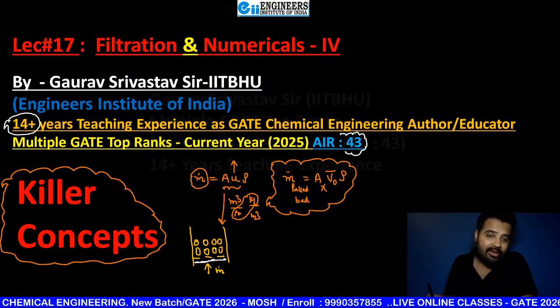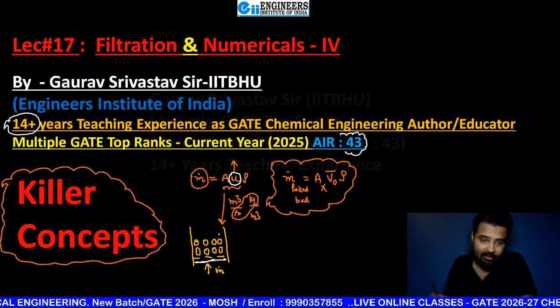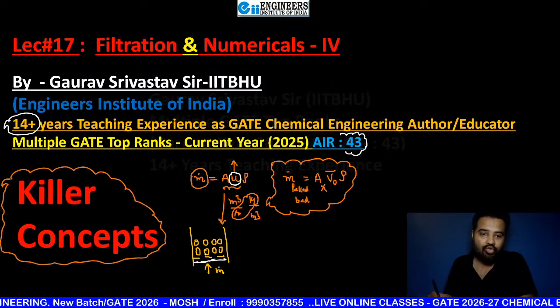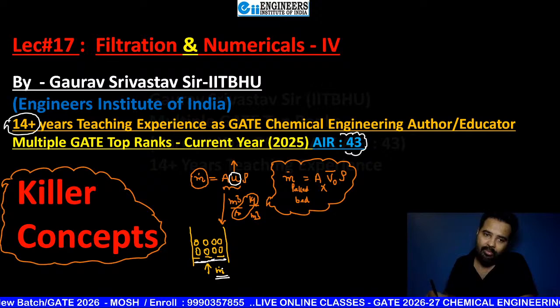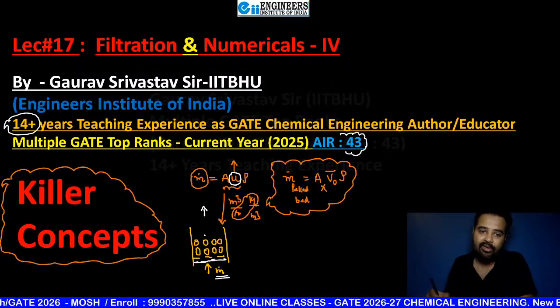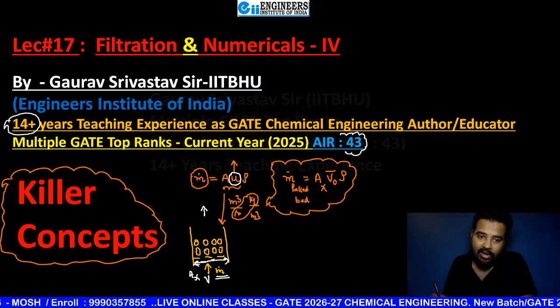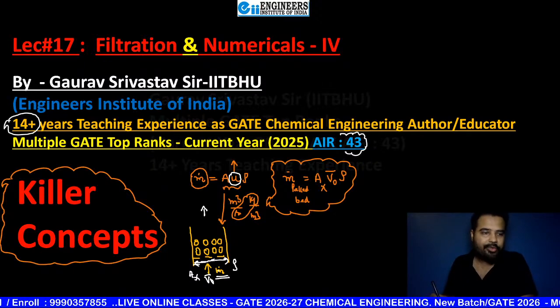Only the difference is that inside there will be more turbulence, because the effective area when it enters into the packing will decrease. So here velocity will increase. Only these things happen after entering. But you know, if 10 kilogram enters from here, then definitely 10 kilogram will exit from here if the process happens at a steady state, beta. So that's why here you multiply A_x, that is the cross sectional area of the tower, with the velocity, that is v naught bar, the superficial velocity, multiplied with the density of this fluid. Okay,